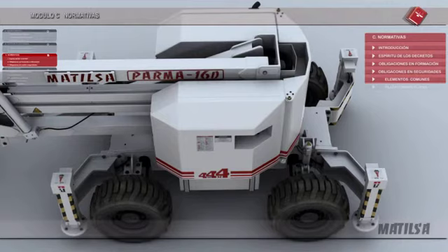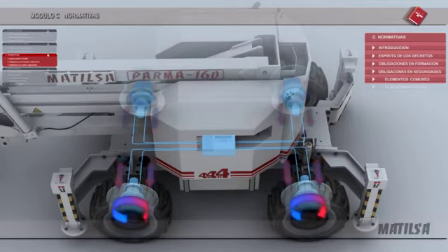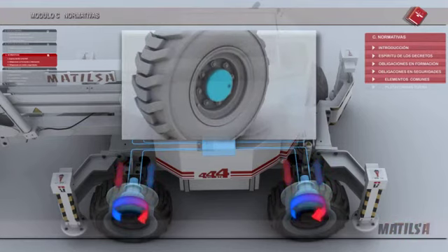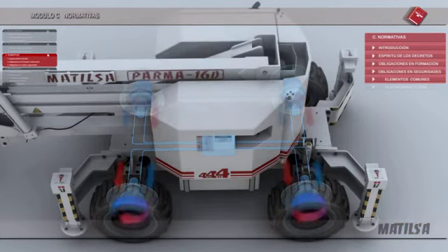The self-propelled system on these machines may be of two types. Hydraulic hydromotors. Thanks to a hydraulic circuit, the hydromotors create a circular movement that gives traction to the tyres. The unblocking procedure consists of loosening the screws that are to be found on the lid of the transporting hydromotors and to turn them over onto this lid in order to unblock the machine. Then the machine may be retrieved from where it has broken down and may be causing a hindrance.